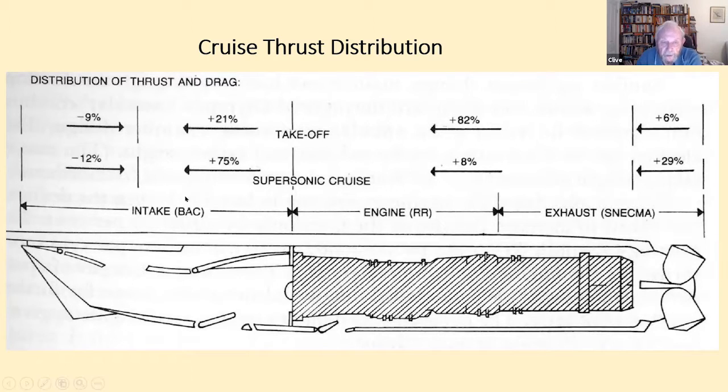The net thrust is a lot lower than the gross thrust which is produced because of the ram drag. So it does mean that if you lose 1% of gross thrust efficiency on either the intake or the nozzle, then the loss in net thrust is about 2.5%. So again, I'm just really saying that the intake efficiency and the nozzle efficiency are the important features.